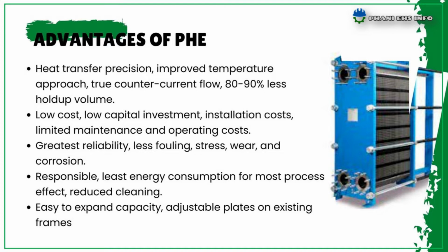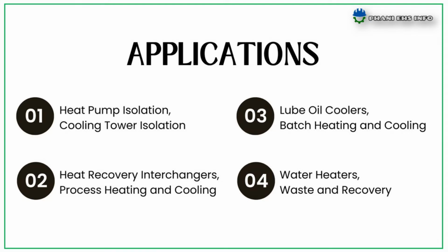Advantages of plate heat exchanger: heat transfer precision, improved temperature approach, true countercurrent flow, 80 to 90% less hold-up volume. Low cost, low capital investment, installation costs, limited maintenance and operating costs. Greatest reliability, less fouling, stress, wear and corrosion. Least energy consumption for most process effect, reduced cleaning. Easy to expand capacity, adjustable plates on existing frames.